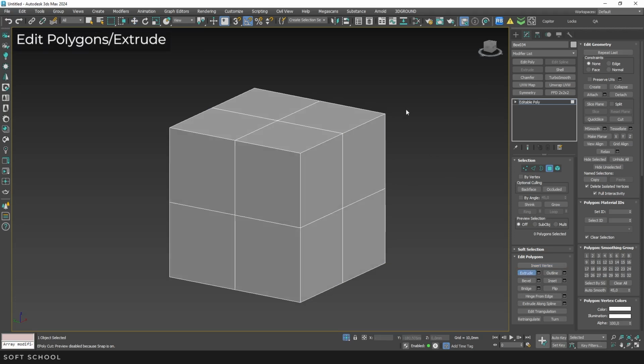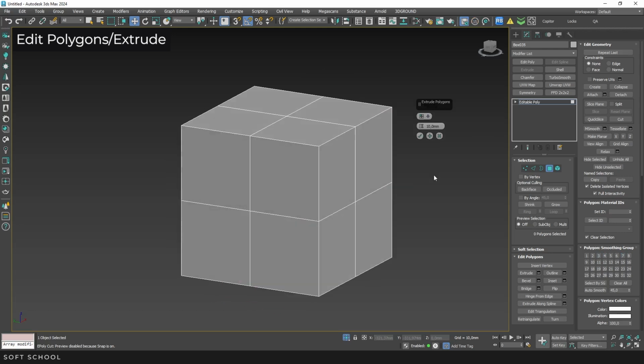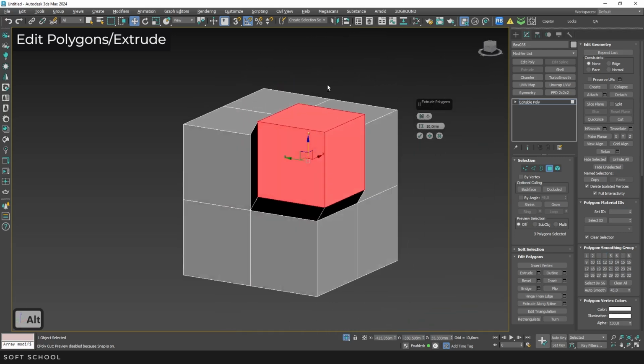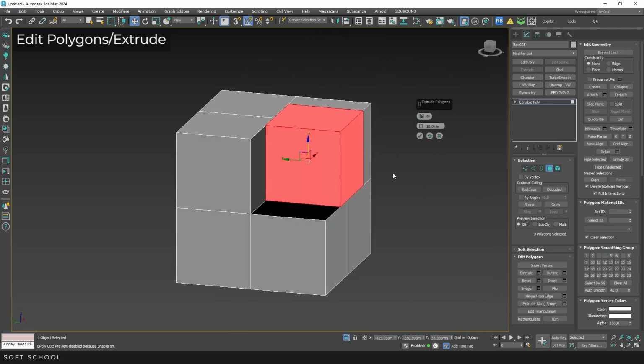The Extrude tool has manual extrusion along the first button's vector, and a settings window that activates dynamic selection, allowing real-time changes. A feature of polygonal extrude is working with selected polygons together. The first mode works as a group, summing all adjacent polygon normals and extruding along this vector. A tip: if you click in the wrong place and lose the selection or select something wrong, Ctrl+Z works for most 3ds Max operations to revert the selection.